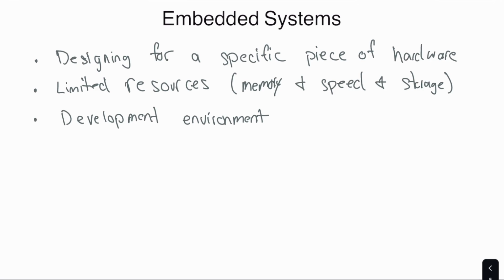That means we have a lot more limited functionality on how we can monitor the output, whether we can use print statements or something like GDB. We can use those tools, but in a much more limited fashion. We also have a less standardized way of interacting. And by that I mean we're not using a mouse and keyboard to control the microcontroller. Instead, we can only send commands over Wi-Fi or upload new programs over serial.